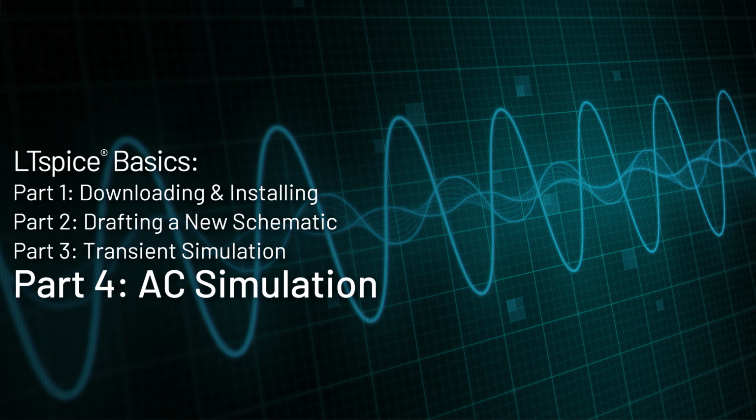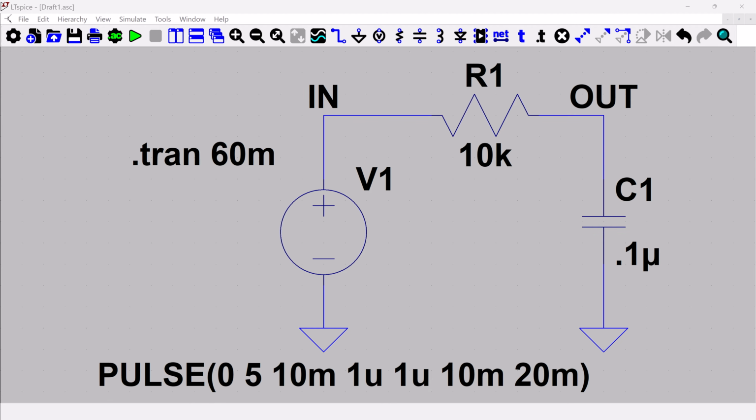In the last video, I showed you how to take this RC filter schematic and run a transient simulation on it. In this video, I'm going to show you how to run an AC simulation on this same schematic. So the two things we will need to run an AC simulation are an AC input source and an AC simulation directive.